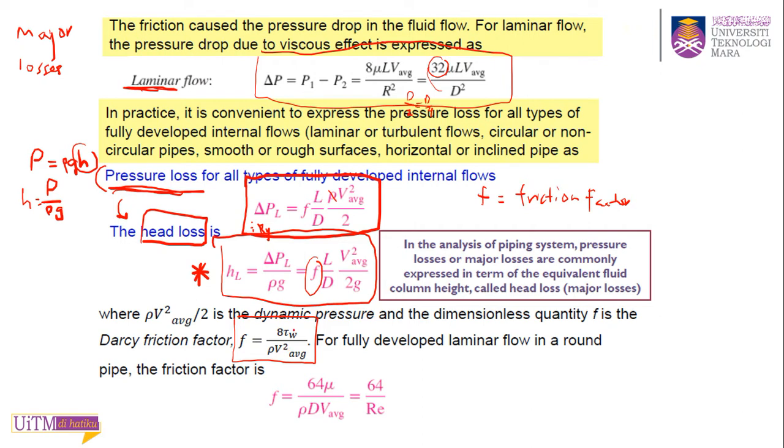But we can use a much simpler equation, thanks to our old generation, who investigated this and studied this chapter. The friction factor for a laminar flow is just 64 over the Reynolds number. So lastly, the equation will be much simpler, very simple.